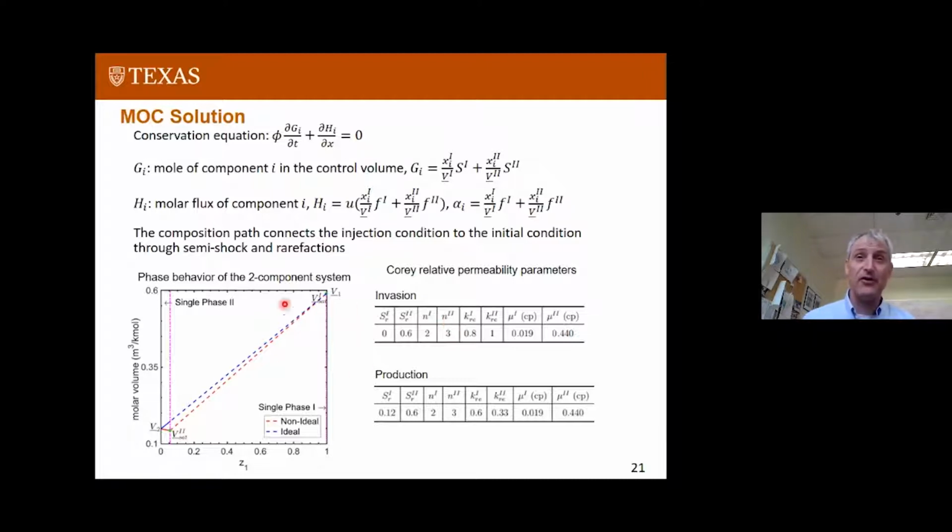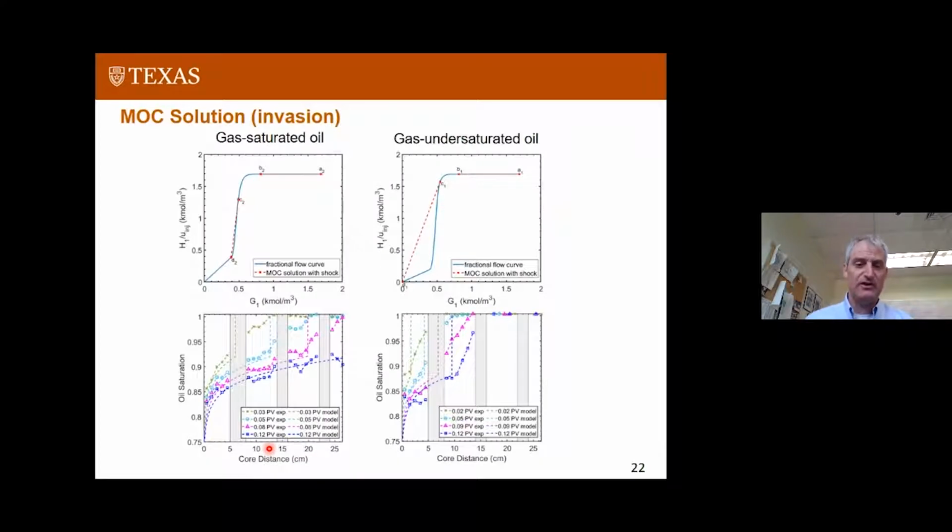You have to be very careful of how you handle all the compositions, because now some of the gas is dissolving in the oil, and you can set up how the molar volume changes with the composition. You can put this all in a model that matches our data. You can find all the fractional flow waves, as we like to do, those of us who like to think theoretically about what's taking place, and we can model it analytically and compare the model to what we see experimentally.